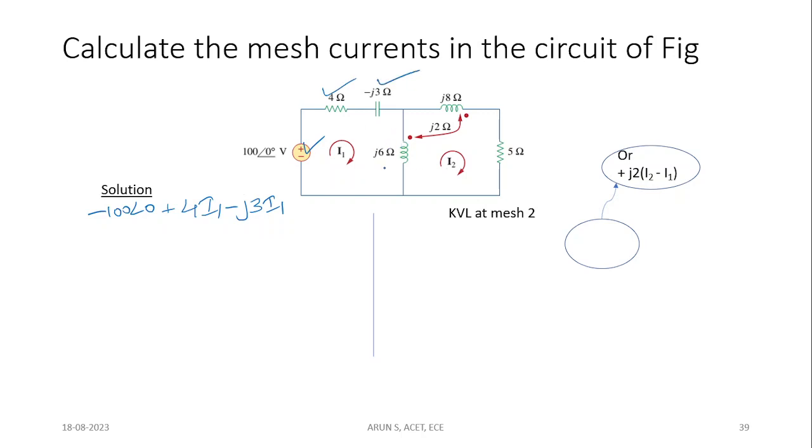So now we got a coil. Through that there will be a current flow. Which current will flow, whether I1 or I2 or both? So we know that if I consider the downward direction, what current will flow? I1 minus I2. This we can identify by simply applying KCL at this node, because here we have current I1, here we have current I2, and in this direction let us assume the current is I. So we can write I1, I is entering, so plus I1, I2 is leaving and I is also leaving. So I will be equal to I1 minus I2.